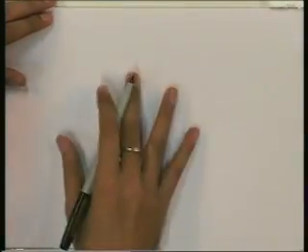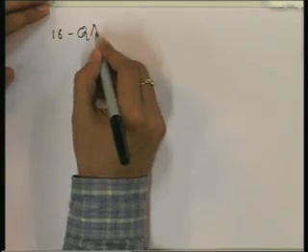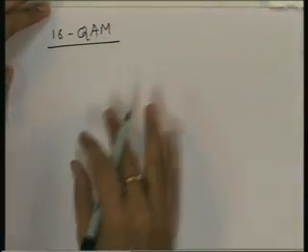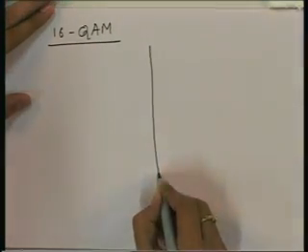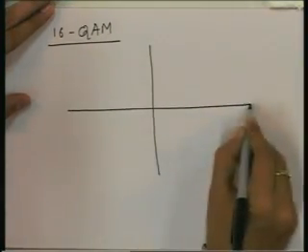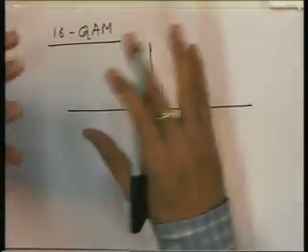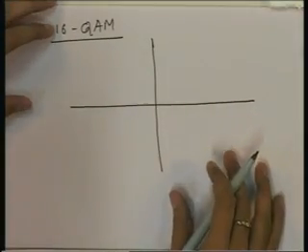Then let us see another. What about QAM? Suppose we have 16 QAM. This is not sequential, so this is quite nice. Even though this is not sequential, all the neighboring points can be mapped in such a way that all the neighboring points have only a difference of 1 bit.